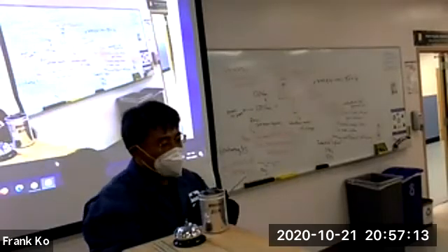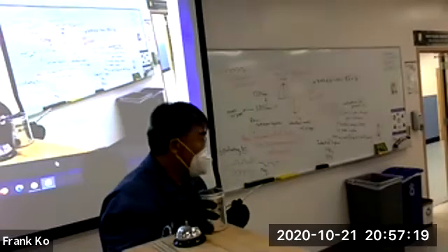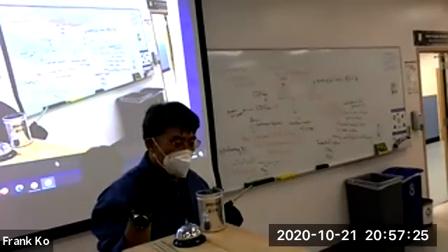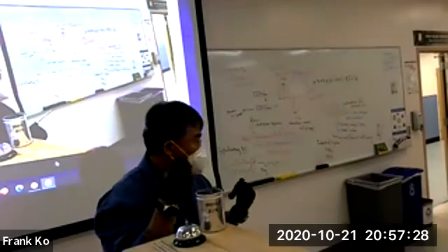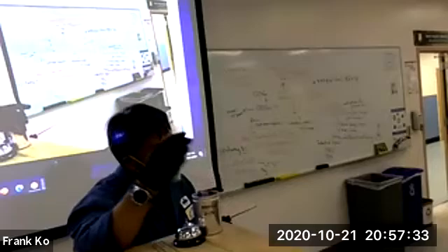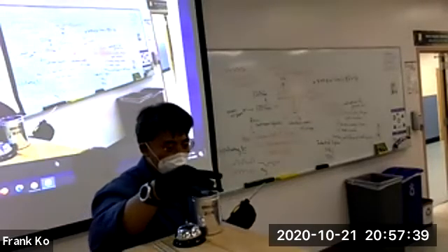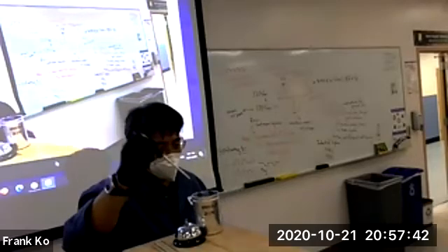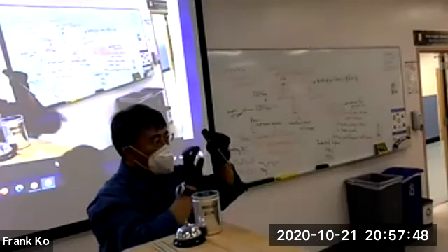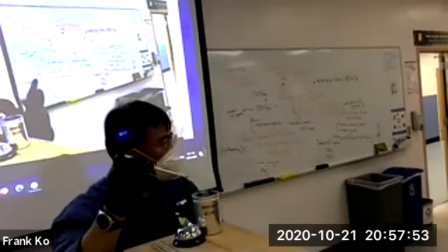It is now discharged. Now you generally don't want to do that to any large capacitor because the spark is not good for this capacitor, because capacitors really ought not to be discharged that quickly. On a workbench for technicians, if they encounter large capacitors in recycling, they have a special discharge probe. It looks like a cattle prod, and one end of it will attach to the ground. The other end, the metal probe, will come and touch this. But in between the ground wire and the probe, there is a huge resistor built into the handle, and that will help dissipate the charge safely.